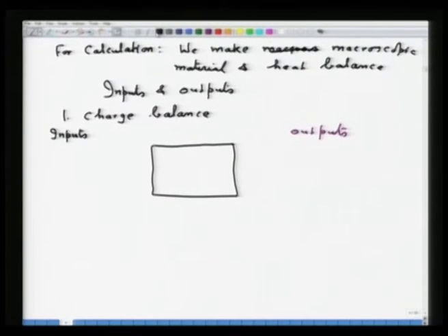Now, in the blast furnace iron making, the input consists of iron ore, of which the composition should be known. Also, input consists of coke, of which composition should be known. So, iron ore can have Fe2O3, SiO2, Al2O3 and so on. Coke can have carbon, you should also know SiO2 and what other composition. So, their amount and composition should be known.